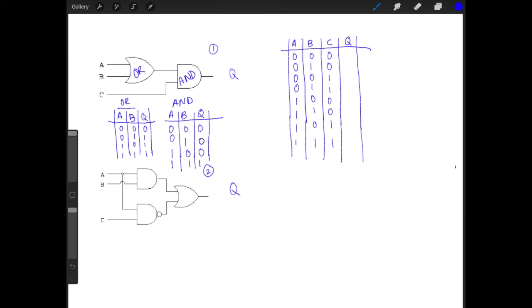So now that we've labeled all of our gates and made a truth table to represent them so we can reference it later, now we'll actually go through all the different scenarios in our truth table and figure out what Q would be. In the beginning, I suggest labeling each of these inputs on the diagram and then seeing Q from there. Later on, you'll be able to really understand the different behaviors of the gates without having to write them all out, and you can just write it straight into the truth table. But for now, let's write it out in the diagram.